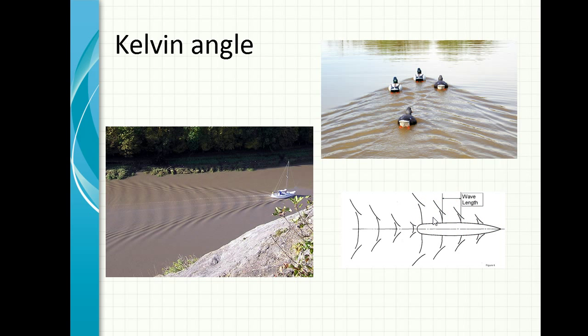Thereby you can reduce some wave-making energy. So that is the principle behind the bulbous bow, getting some benefit out of reducing the wave-making energy loss, which increases the resistance. That is why a bulbous bow is provided.